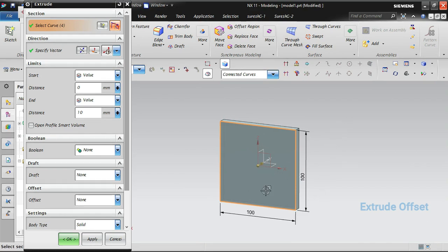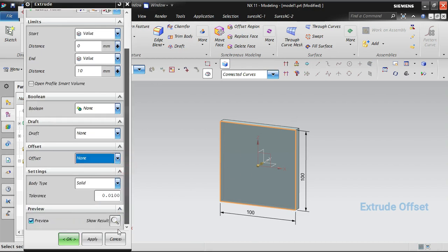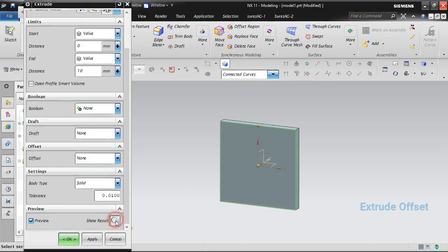So that means internally, I'm going to make some hollow. Okay, so internally I'm going to make some hollow. I wanted to make a hollow rectangular cube. Okay, so in that case, how I can go for it is, so you can go for this is in the none option so that it creates as it is. Okay, I will give preview. You can see now this is how it will create.